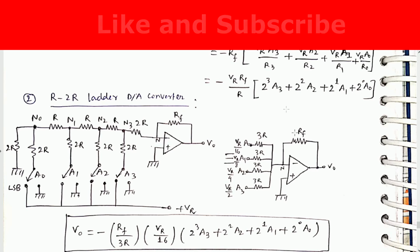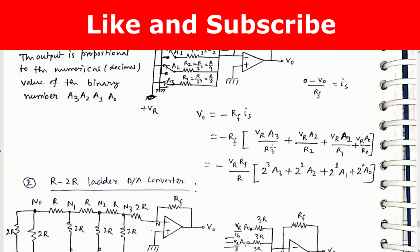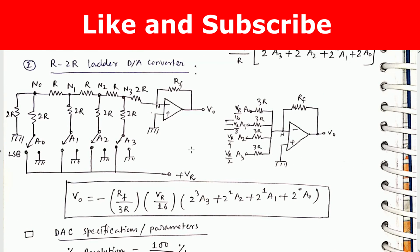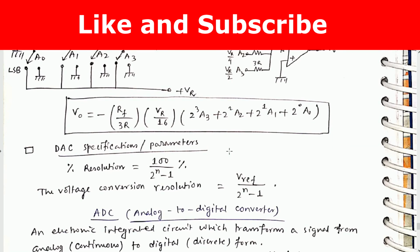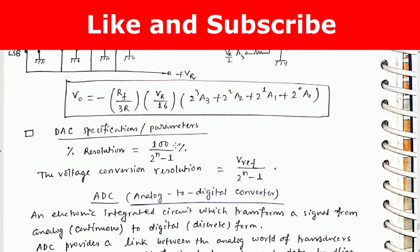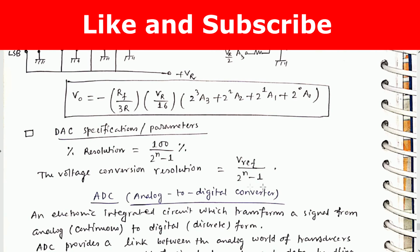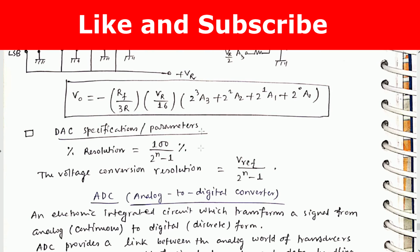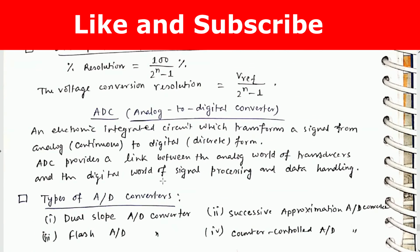I will not recommend you to remember so many things, but try to remember this, or at least before you enter the examination hall, just look at these formulas and you can remember them. It's not so tough. DAC specification parameters: percentage resolution equals 100 by 2 to the power n minus 1 percent. The voltage for resolution is V reference by 2 to the power n minus 1. Very often questions are set from this.